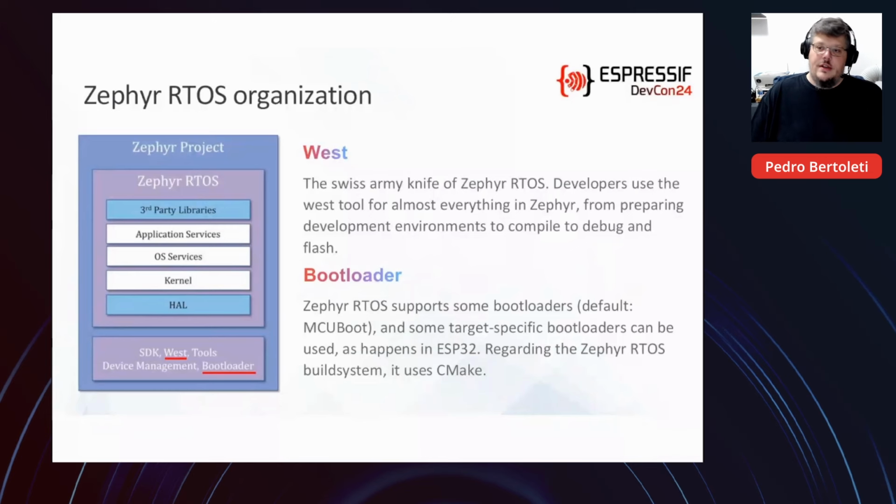And the bootloader, of course, a bootloader is not a specific tool from the Zephyr project, but it's a very special topic here in Zephyr because Zephyr can use target specific bootloaders or a default bootloader. Zephyr uses MCUboot as the default bootloader, but it can use, as I said before, some target specific bootloaders, as happens in ESP32. And also, regarding the build system, Zephyr RTOS uses CMake.